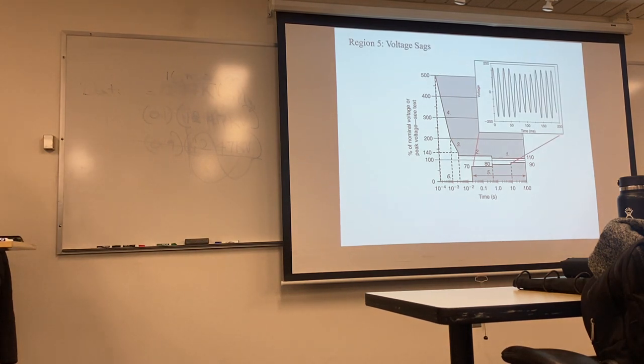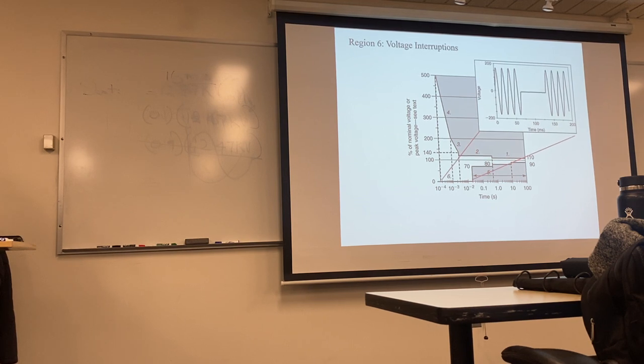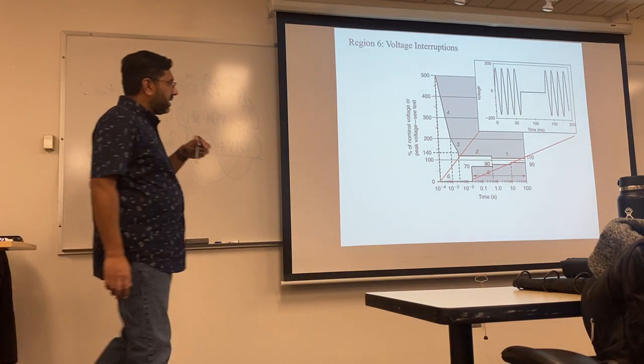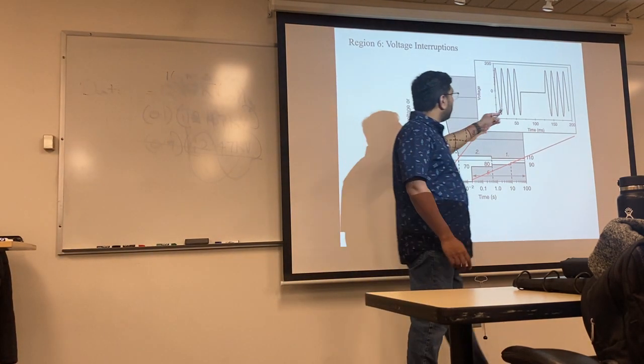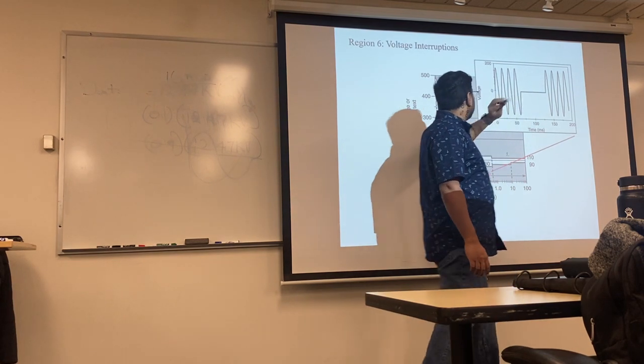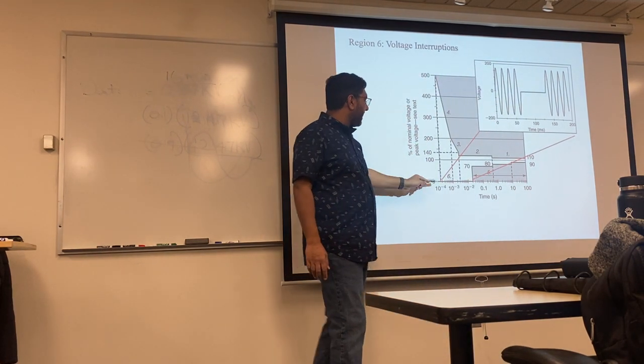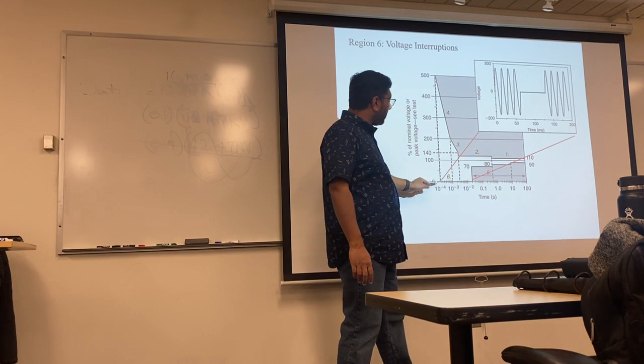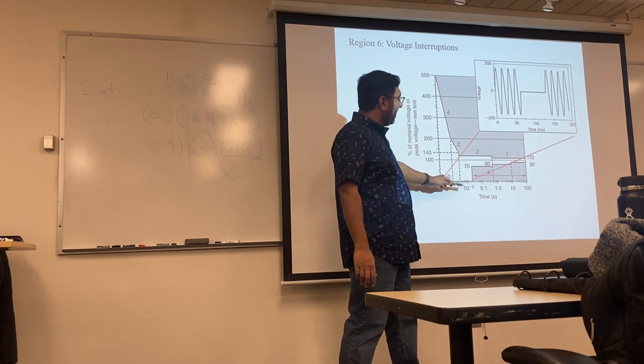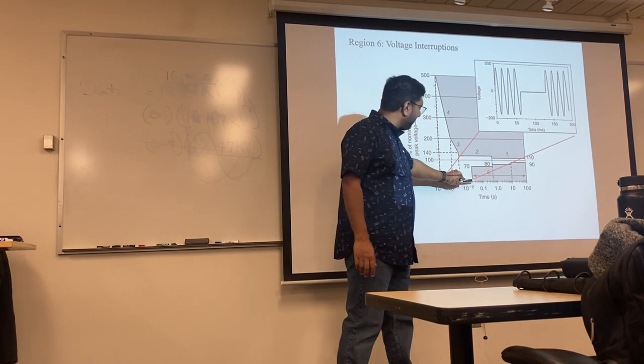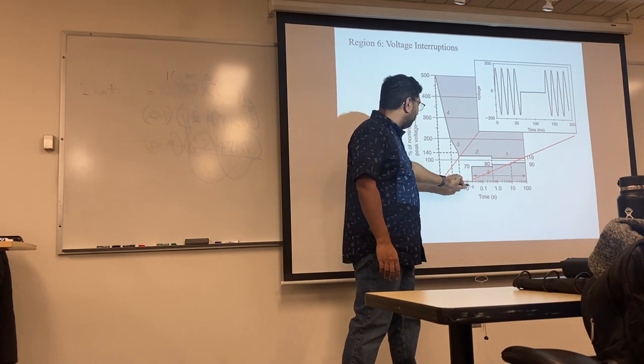And of course, voltage sag means the voltage is below the expected voltage. This is an interruption, like the voltage literally collapsed. Looking at this, I'm going to say it's a short-term interruption, not a major outage, because it just happened for so many milliseconds.